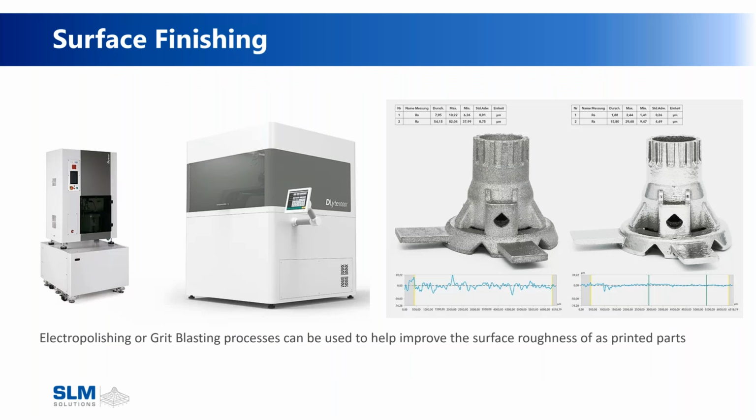And then surface finishing. This is fully dense metal when we're done. So you're grinding it, sanding it, electropolishing, bead blasting. They all work just as well as any traditional material. One of the systems that we like to use and like to see a lot is this electropolishing system, because in a very short order of time, you can reduce the overall surface roughness in a very uniform fashion on additively printed parts.